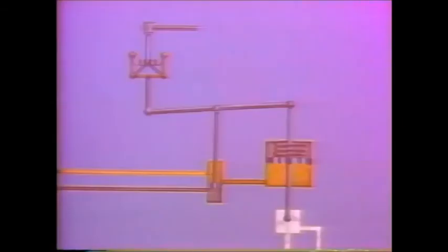Through this method, a certain amount of feedback is given to the control system to allow the speed adjustments to occur in small increments. If adjustments were made too quickly, the control system would fluctuate up and down while it searched for the proper speed. This search is called hunting and is undesirable because it causes rapid speed changes in the turbine.